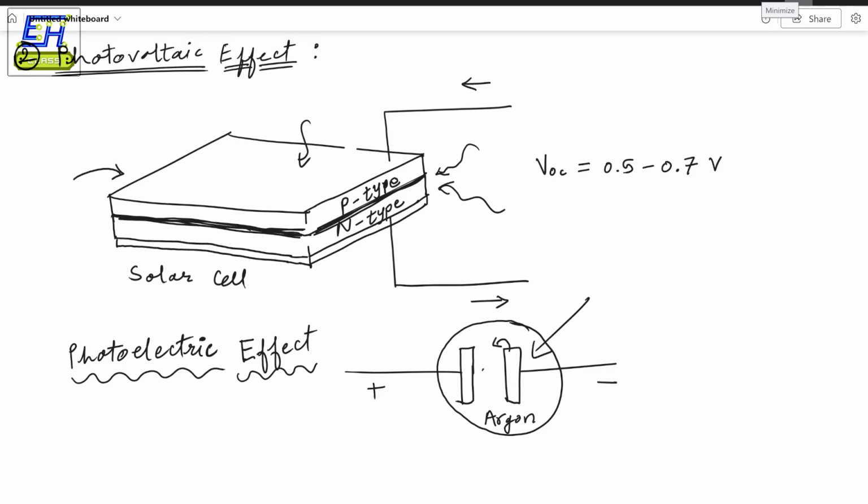And this electron emission really depends on the kind of material you are using. So let's just assume that this terminal will emit the electrons, and then these emitted electrons will follow the electric field that is already present and will move to the opposite side. Because we now have flowing electrons, definitely in the external circuit we'll see some current flowing, and this current is what we measure. And this is nothing but because you are getting current when you have some light. So this thing can essentially be used as a light sensor, and it is known as a photocell.